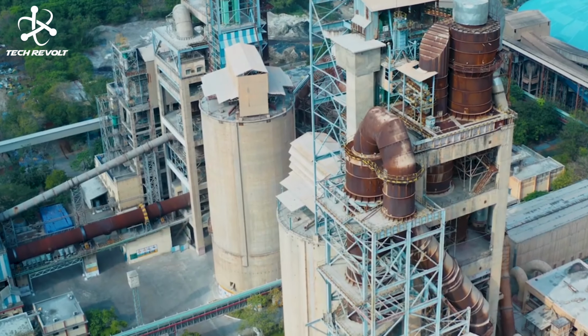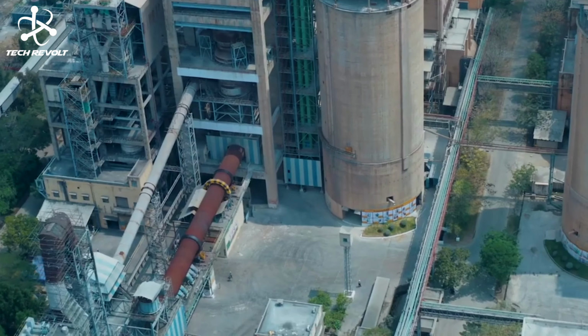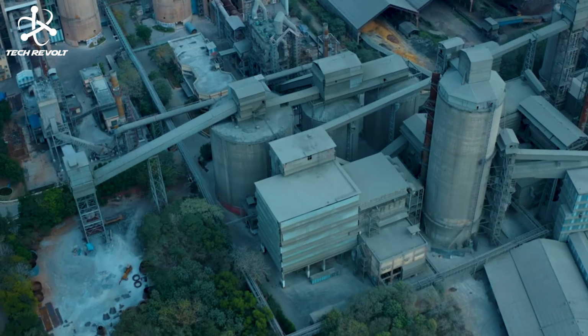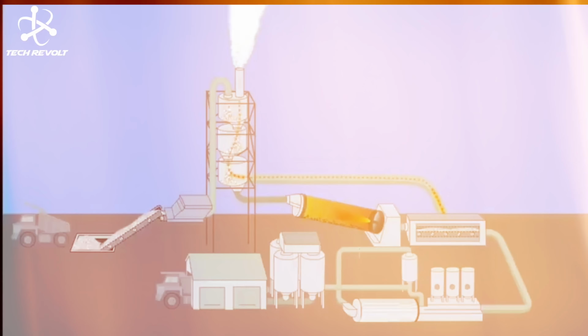Dust emission from cement kilns can be a serious environmental concern. In populated areas, it's usual and often compulsory to fit cyclone arresters, bag filter systems, or electrostatic dust precipitators between the kiln exit and the chimney stack.